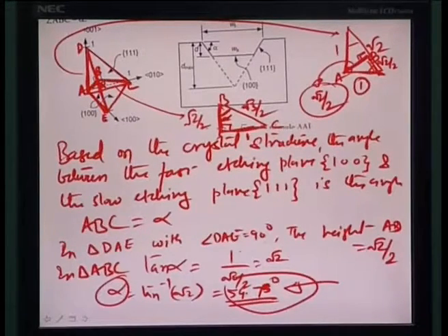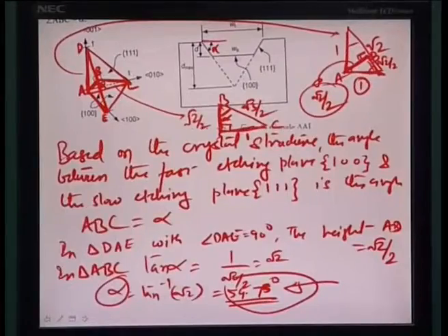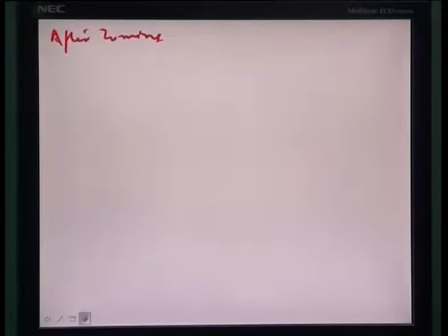The angle of the plane finally formed in this anisotropic etching process, with the direction of the face of the wafer, is really 54.74 degrees. This alpha here is the phase direction of the wafer, this is the angle of the plane. So, this is also the 111 direction, alpha is 54.74 degrees. And let us find out what happens after 20 minutes.